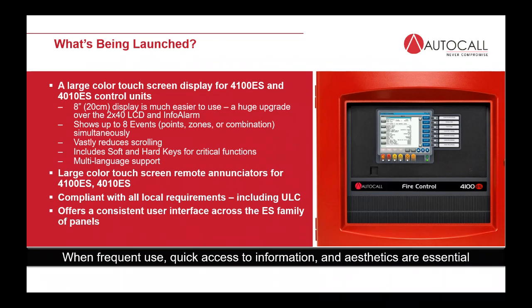So with the ES touchscreen display for 4100 and 4010ES, you will have the option of using either the soft key that's above it, just like the 4070S, or if you press on those icons, those are hard keys that'll be able to perform those functions. So that gives a much higher level of reliability in case the touchscreen goes down. People get concerned: what if it fails? You'll still have those hard keys, and vice versa. If the hard keys for some reason would fail, you've got redundancy on the touchscreen display. So that's a key functional difference from the 4070S.